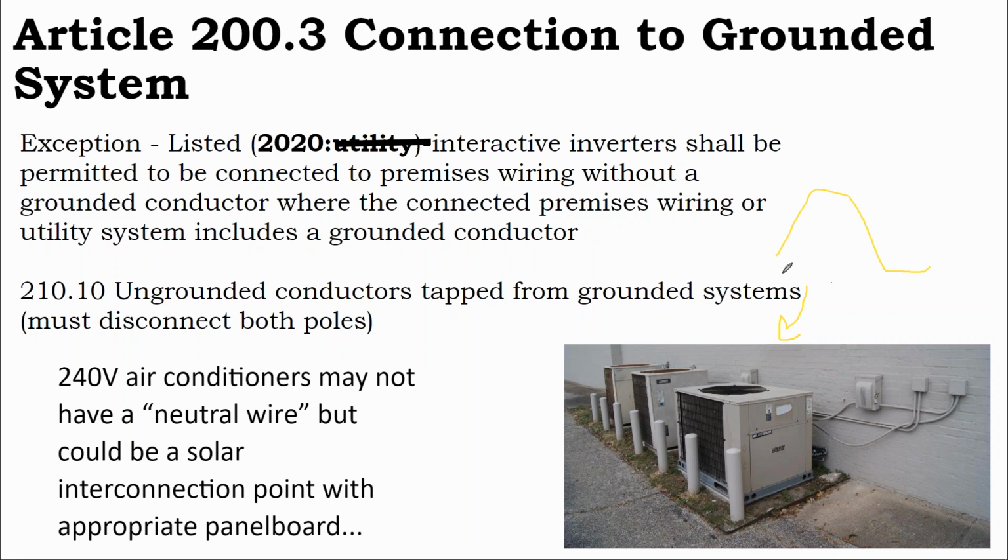a 240 volt circuit, which is actually two sine waves that are equal and opposite each other, and so they always have that 240 volt potential already. And so the nature of the 240 volt potential, it's 120 volts up and 120 volts down. We have that voltage potential, and voltage can flow across those two phases.